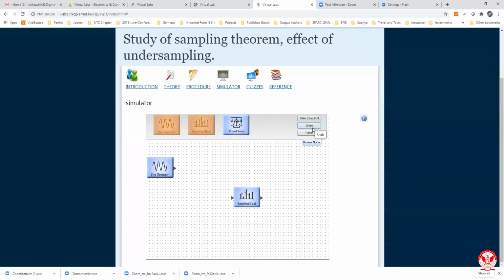And how can we make the connection in a better way? We select some line here. So this is the better way that we should prefer, and avoid this cross type of connection and connecting in midway like this. We do undo here. Here we can see we start the connection here, and if we just drop at any point, it becomes red and still remains red until it is joined to either the input of a block or the output of a block.